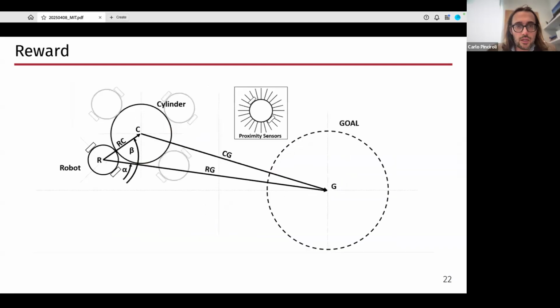So what the robots can do is essentially sense their vector to the object, not necessarily to the center of mass of the object. By the way, we do not assume that the robots know the center of mass of the object. They have a gripper that basically can sense the push and pull force that a robot is exerting on the object. And then the robots obviously have wheels, and they can rotate their body independently with respect to the point of attachment to the object.